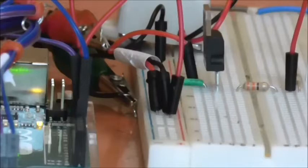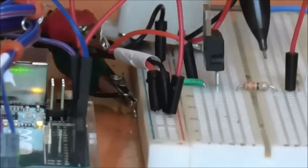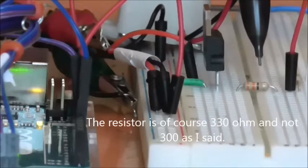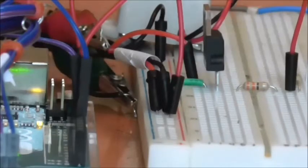And as you can see, what we've got left is the transistor that we've had all along, which is of course the subject of this discourse, and a 300 ohm resistor there at the base. We've got an LED as we had before, and a 560 ohm resistor driving that, and of course our buzzer here as the emitter follower. I'll zoom out a little bit more now.